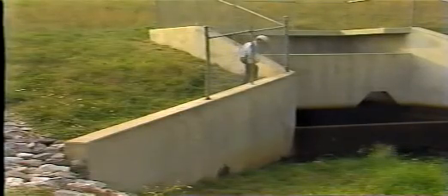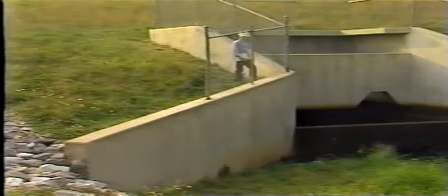Another deficiency to look for is structural movement at concrete joints in walls and floors. Structural movement may occur as differential movement, separation at joints and cracks, or compression evidenced by crushed concrete or extruded joint filler. Look behind chute or channel walls for depressions or sinkholes, and look to see if weep holes and drains have become clogged. Check exposed trash racks for debris that may restrict flows. A decrease in discharges at the same reservoir level may indicate blockage of the intake. Also check to see that trash booms are afloat and have not separated.